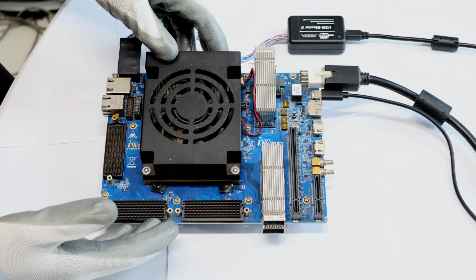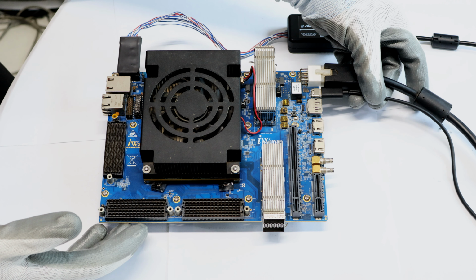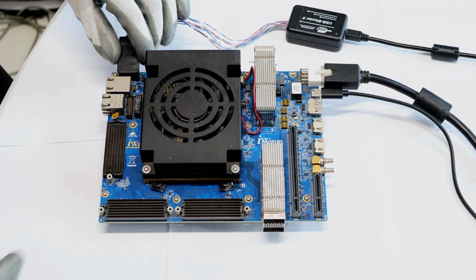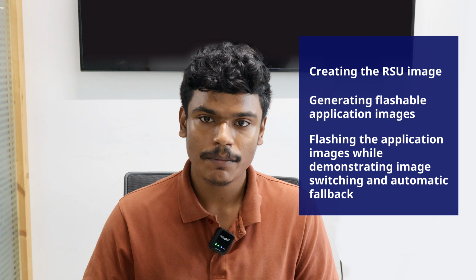So this is the Agilex 7 dev kit and I am using the 15 volt 22.7 amps power supply, and this is the UART that I've connected, and I'll be using Altera's USB Blaster for flashing the initial RSU image. We'll cover the complete RSU workflow in 3 parts: creating the RSU image, generating flashable application images, and flashing the application image while demonstrating image switching and automatic fallback. By the end of this video, you'll understand how RSU enables reliable in-field FPGA updates without requiring the entire QSPI device to be physically reprogrammed.